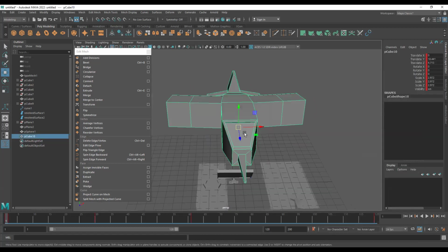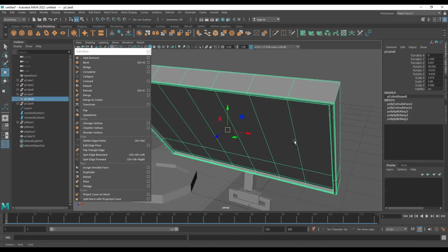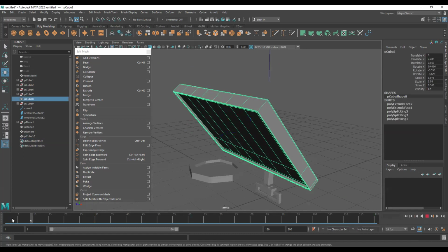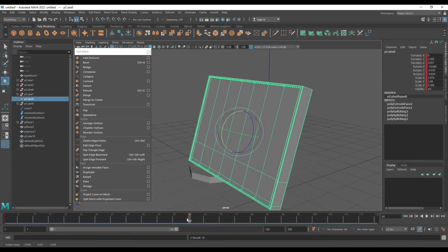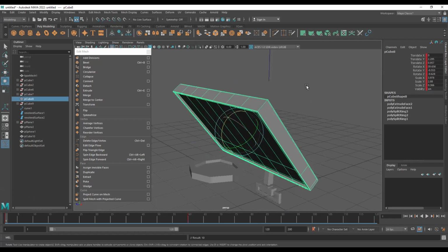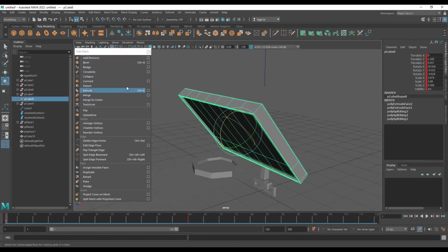Okay, you can try the animation. It's very simple. So first, select the object and move the frame to the first frame. When you press S, you can see the rectangular mark is highlighted, and you can see the rectangular mark highlighted over here. And go to the last frame, or wherever frame you want to go, and then move the object, then press set key. So first frame, first frame. That's it.